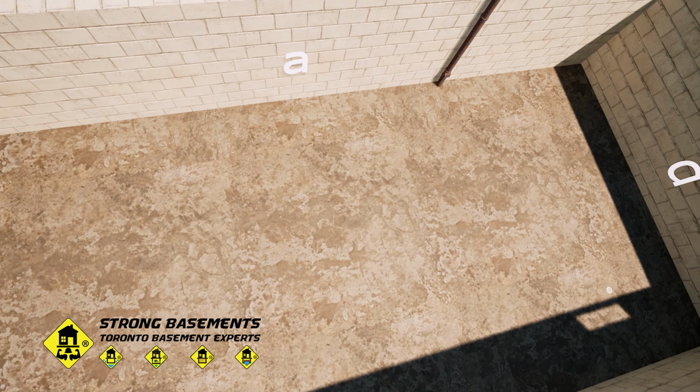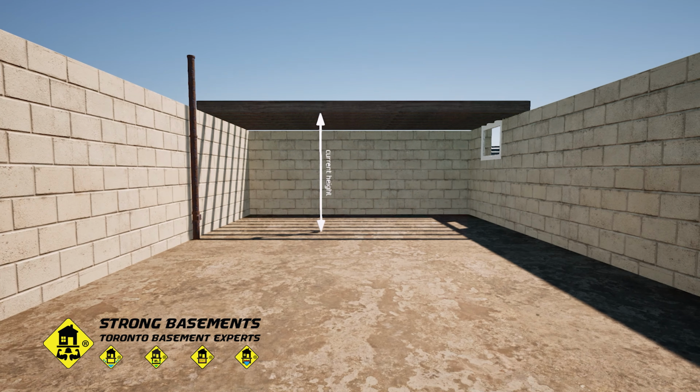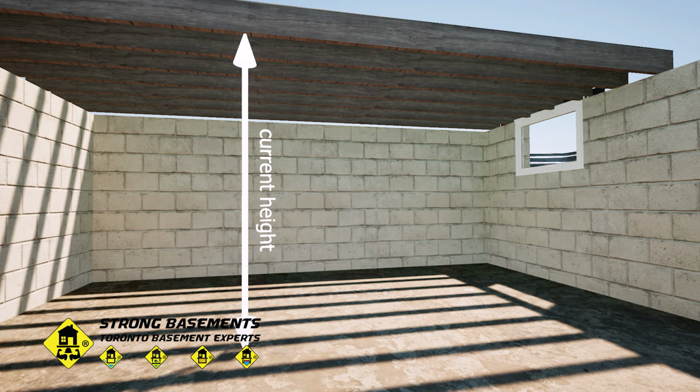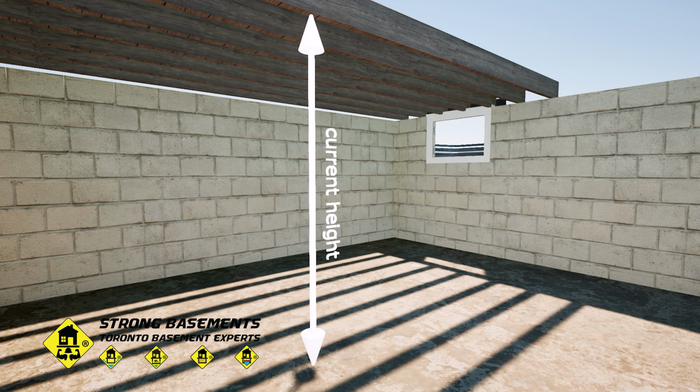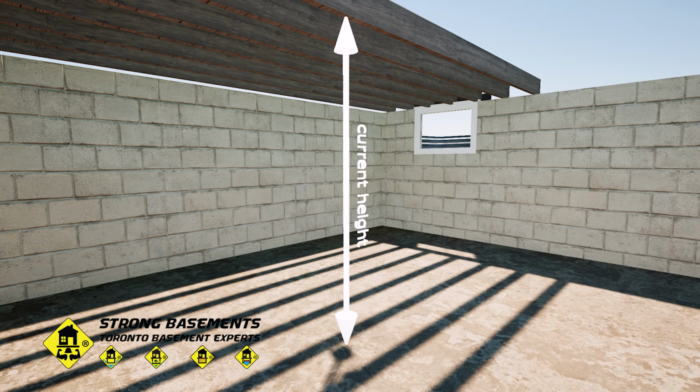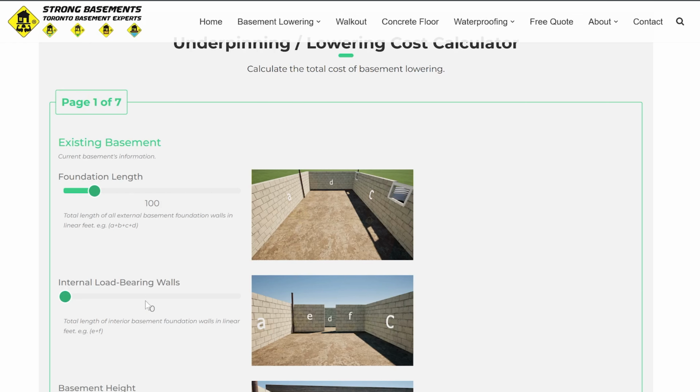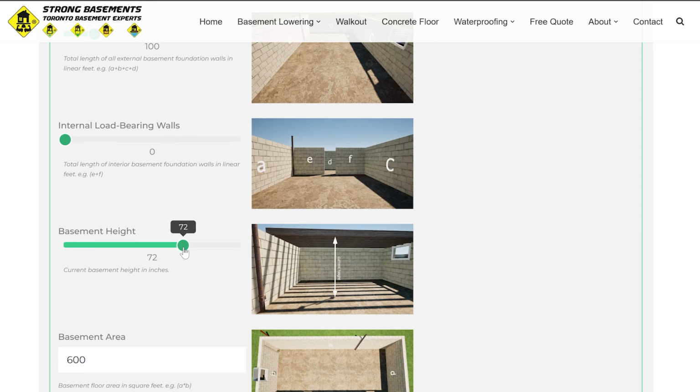Next, you'll need to determine your current basement height. Simply measure the distance from the concrete floor up to the bottom of the ceiling joists. In this example, the height is 72 inches, or exactly 6 feet. Once you have your number, enter it into the current basement height field in the calculator.